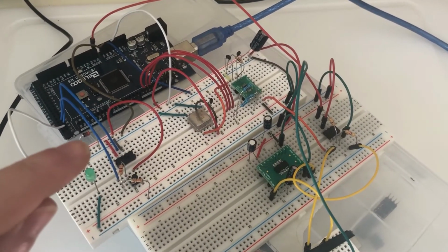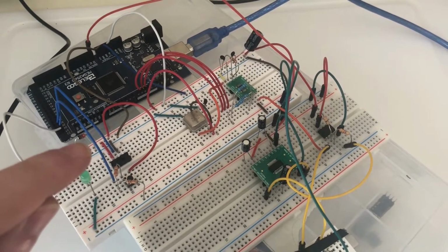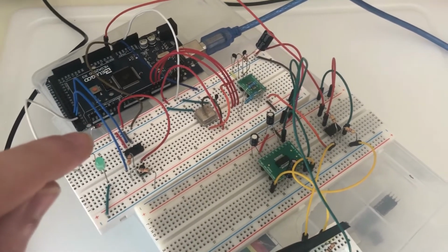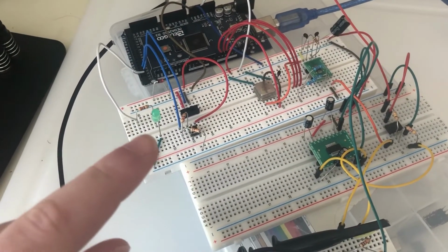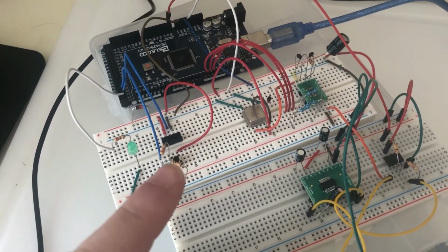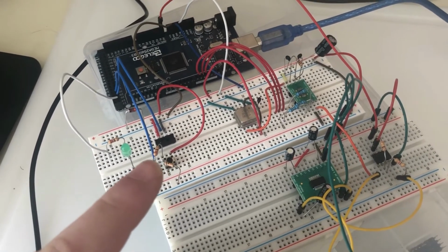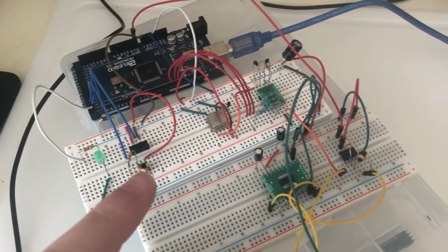And then here we have a 5.1 volt breakdown zener to prevent overvoltage. And then we have an indicator LED here. So when this button is activated, which is the sweep button, it turns green until the sweep is complete, then